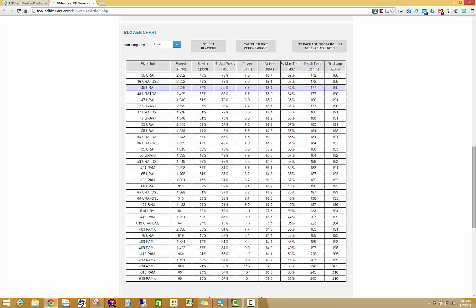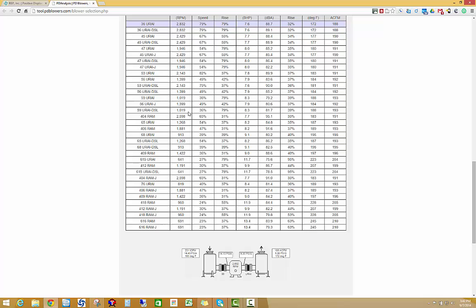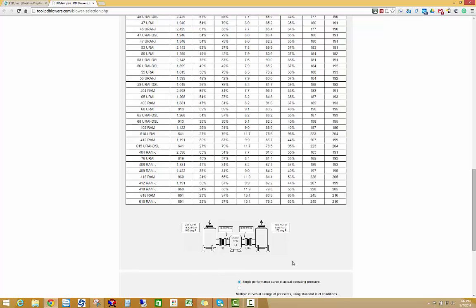You can select different units by just clicking on that particular line, and where that becomes important is down here at the schematic. So based on whichever unit you select, the process conditions change in these blocks. So here we represent 231 ICFM at 14.43 and 100 degrees Fahrenheit. So those are your inlet conditions. We've got a 0.3 psi pressure drop that we put in at the top.